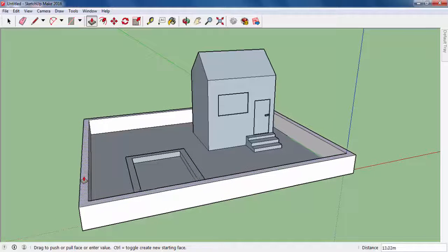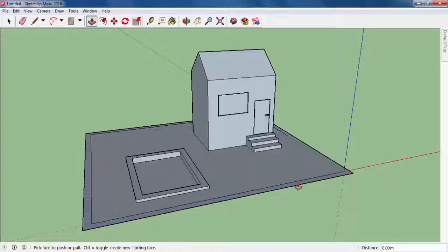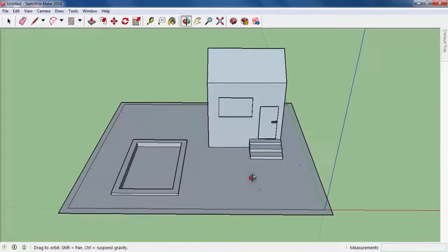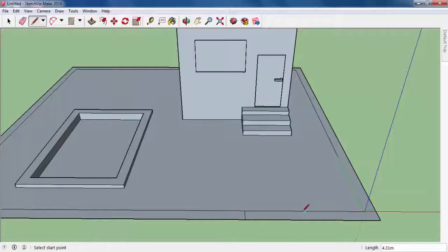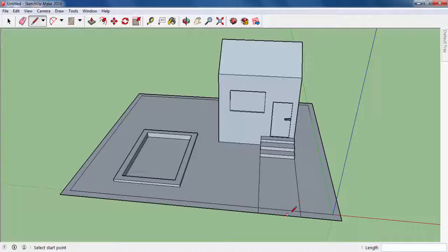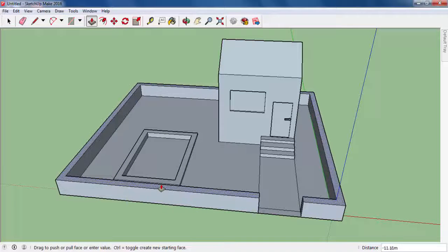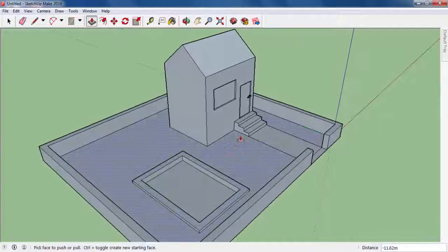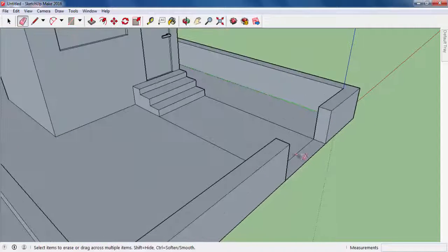They all come together, but I also want to assign this place as the gate of the house. So I will cut these parts, or let me do it like this. I'll do this more symmetric. And now I will come from there to here, and then I will cut this part from the hole so that it won't include this part when I use the push and pull tool, as you see. Here we go. And then I can erase this part. There's the extra line we see.